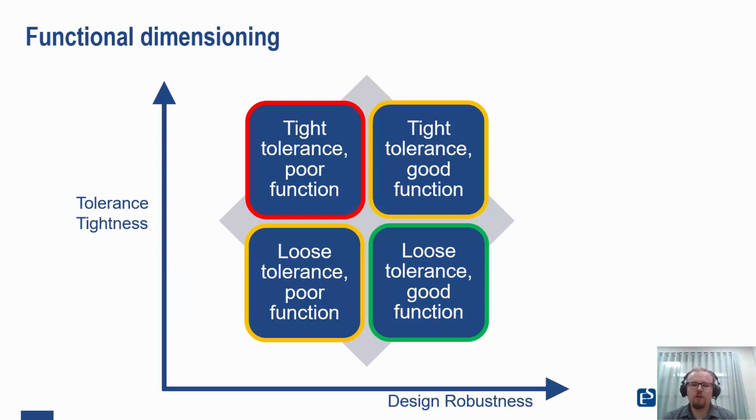We're going to start off by looking at functional dimensioning. By using ISO GPS, we can clearly communicate what is required from a part on the part drawing. For instance, we can specify that a boss must be able to be assembled to a counterpart. If we use coordinate dimensions, this is difficult to express precisely and without ambiguity, which we will explore later. What this means is that our parts will all fit together if they are created to the specification with ISO GPS. But the concept of interchangeable parts has been around since the 1880s.